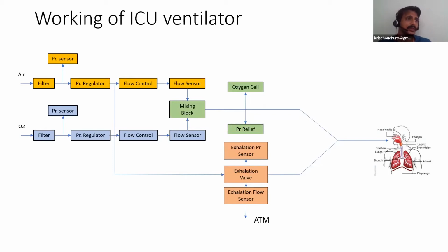So once the pressure regulator brings it down to 50 to 60 centimeters of water, usually there's no regulator that can accurately bring down the pressure from 60 psi to 50 centimeters of H2O, sub 1 psi, in one stage. So you usually have two pressure regulators working in tandem. One of them brings it from 60 to 2 psi, and another one brings it from 2 to sub 1 psi. Usually the latter regulator is more expensive, since those pressure ratings are not common in the market, you do not have enough demand, and they're also bigger and clunkier and more difficult to manufacture.